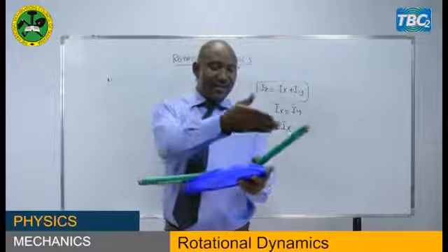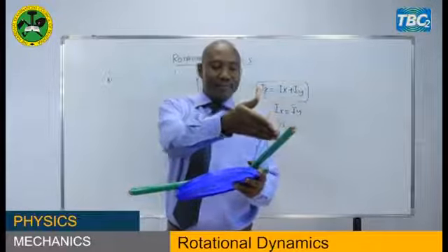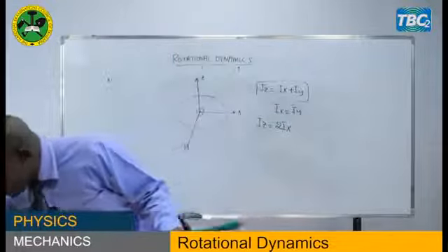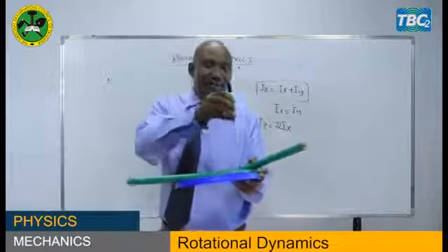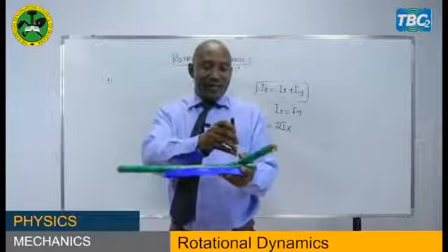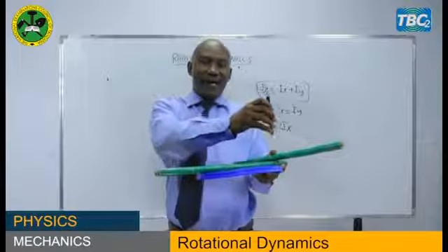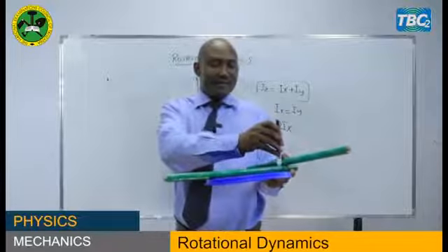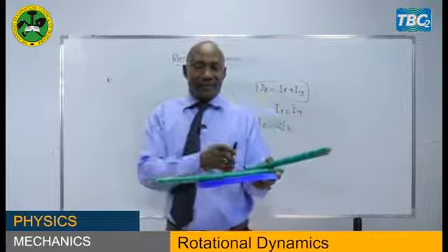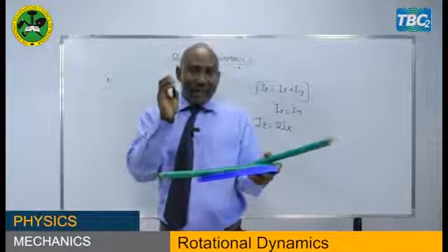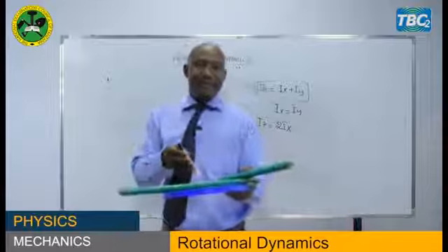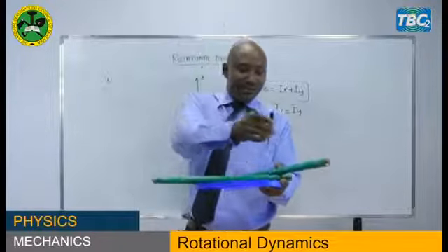And we are looking at the moment of inertia passing through the circumference, but this time it's parallel like that. Provided that the moment of inertia passing through that point, intersecting the two, and perpendicular to the plane is known, that will be our z, Iz. So Iz equals the sum of the two axes. The perpendicular axis theorem applies only when you have two axes which are intersecting, and another axis which is perpendicular to both.